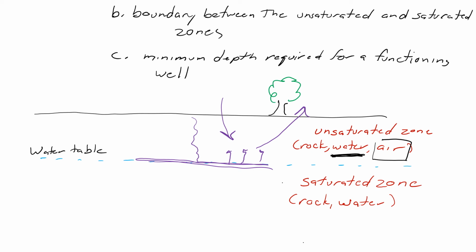So just a few things to think about in relation to the unsaturated zone, saturated zone, water table. All right, any questions? Is that gas that would leak into the soil combustible? Yeah, it can burn, yes. In order to get burning, you have to have oxygen, right? And remember, there's not a lot of pore space in here. So what will happen is sometimes it will ignite, but then it just sort of smolders because it's not getting enough air. Not so common with this, but it happens a lot with coal seams.